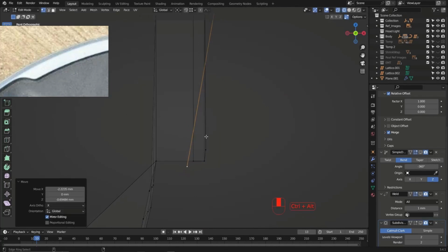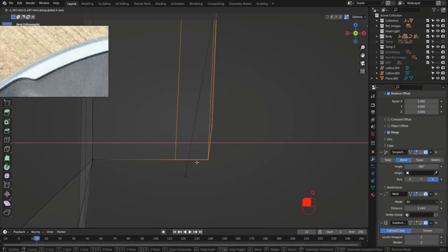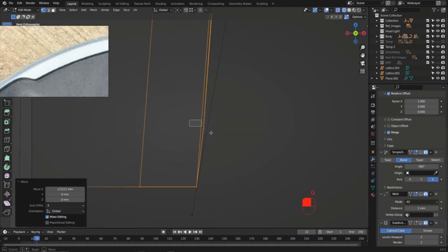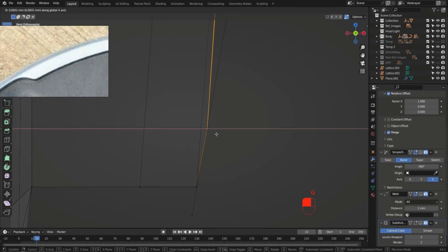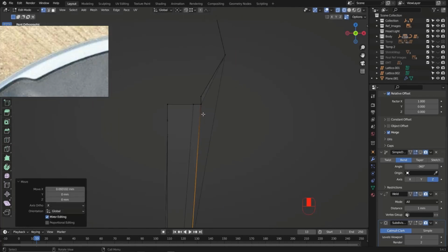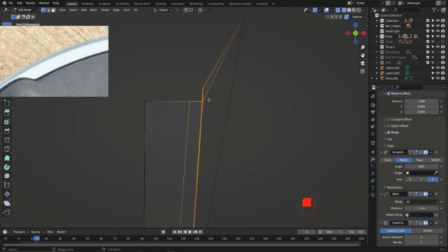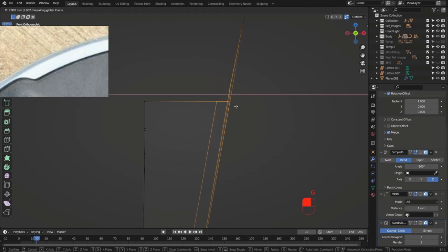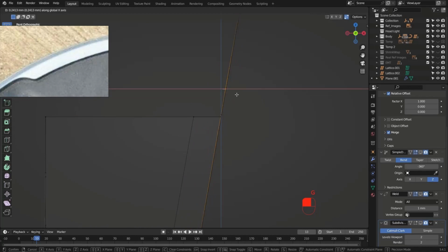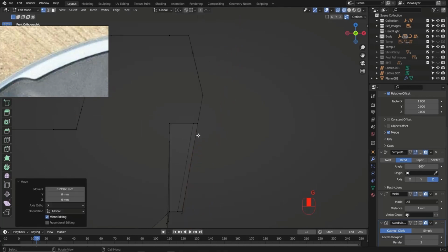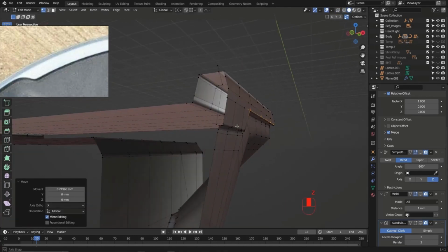All right, I just want to make this area smaller by taking this corner and pushing it back. Let's grab these and hit G and move those over here. This one, it should be moved here, I guess. And now these vertices, G, and let's push those here. And this one, it should be moved right here. Let's see in the perspective what we got.